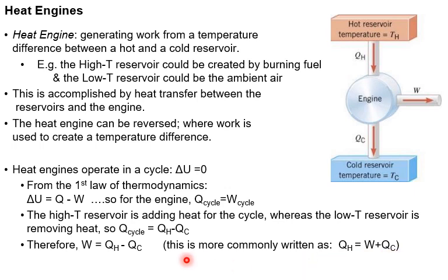The other way to think about it is in terms of the first law of thermodynamics. In that case, you really just want to keep in mind that for a cycle, heat added is equal to work done. And the heat added is going to be the difference between the flow from the high temperature reservoir minus the flow to the cold temperature reservoir. So perhaps this equation is more useful. They say the same thing. It's just a little bit of algebra, and it depends on how you want to think about it, energy conservation or thermodynamics.